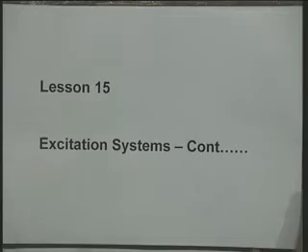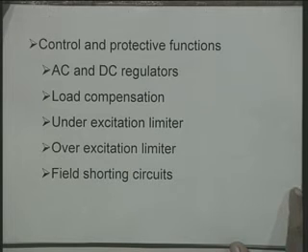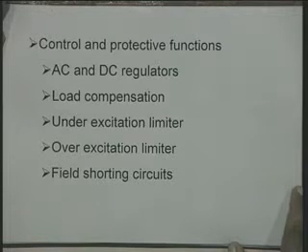Okay, gentlemen, we start with the study of excitation systems. Today, we shall cover the control and protective functions. The control and protective functions provided in the excitation systems are AC and DC regulators, load compensation, under excitation limiter, over excitation limiter, and field shorting circuits.